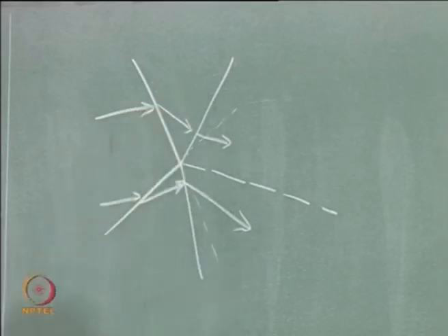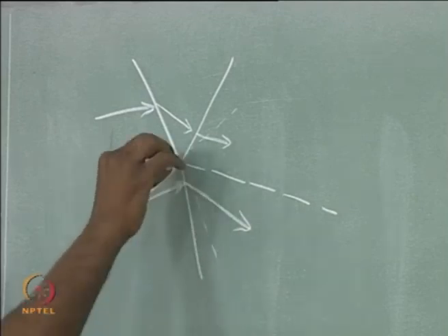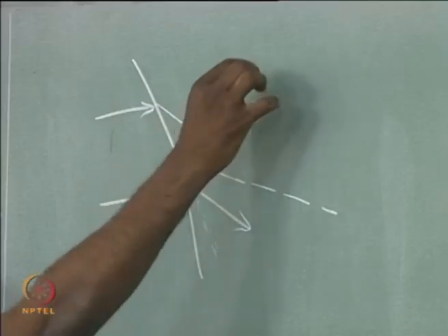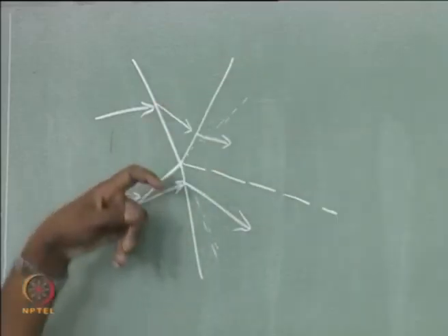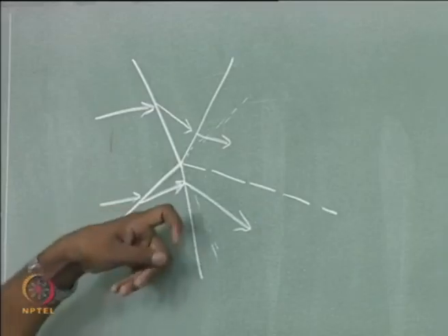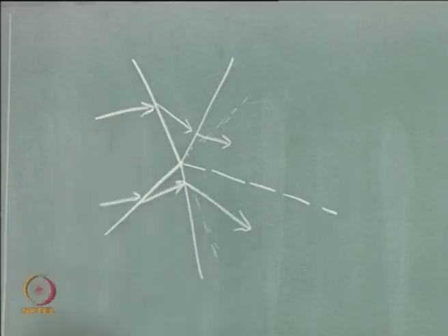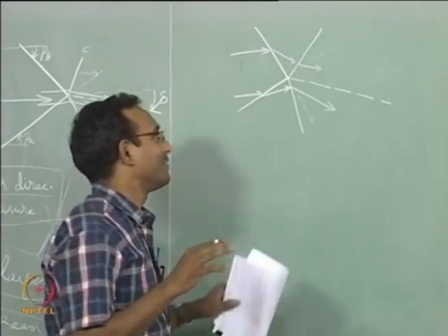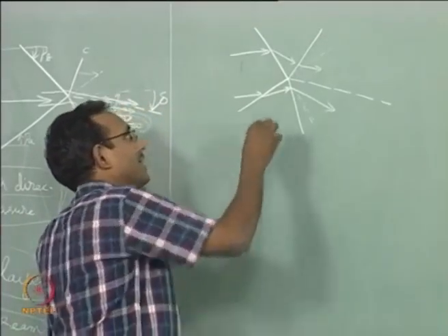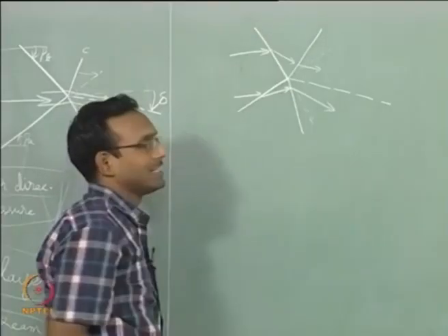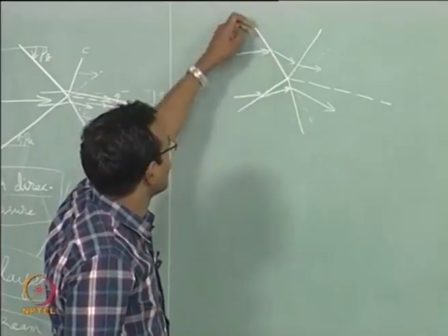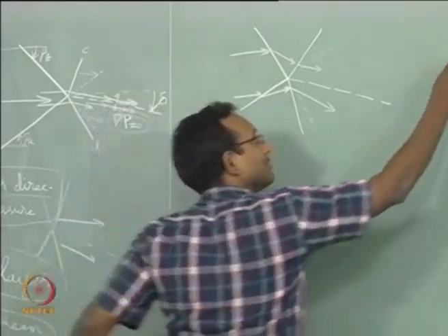But I will tell you a quick way to remember this. I can easily tell that if I extend the original shock on this dotted line here and the dotted line there, I know that the reflected shocks will be ahead, more upstream of that dotted line. A simple heuristic or hand-waving argument will be that I will take this piston analogy, and when the shock is coming through that piston down straight like this, I will draw that picture also.